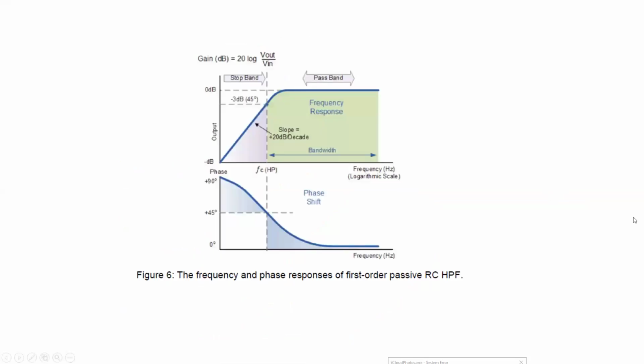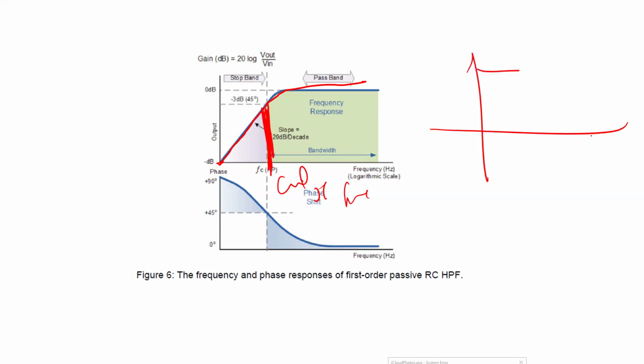Look, see here again. At very small frequencies, it should not pass, and then as we increase the frequency, at a certain point we call it the cutoff frequency. Very important, similar to the previous one. However, there is a big difference. In the case of a low pass filter, all frequencies from 0 until cutoff are going to pass. Anything greater than the cutoff frequency is not going to pass.